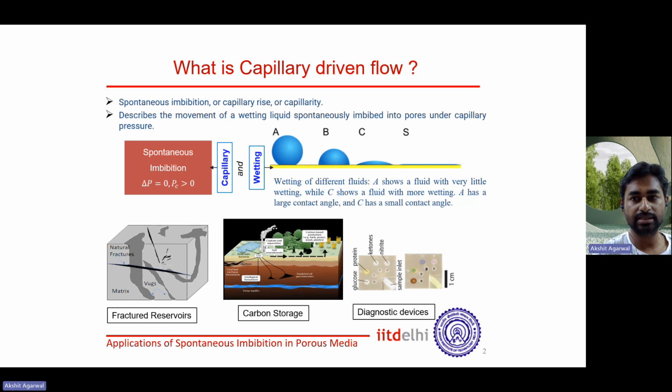Now, the next question is about the wettability. So wetting fluid and non-wetting fluid. The tendency of a liquid to spread over the surface of a solid is an indication of the wetting characteristics of the liquid for the solid. The spreading tendency can be expressed more conveniently by measuring the angle of contact at the liquid solid surface. As you can see in this figure, different types of fluids are spread on the solid.